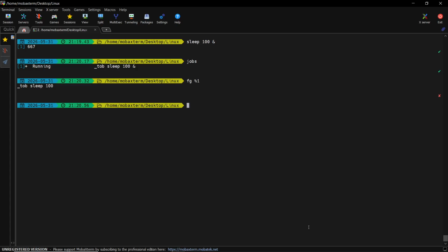Environment variables are important because many EDA tools and project scripts depend on them. If a required variable is missing or wrong, the compile or simulation flow may fail. So DV tools are often dependent on environment variables. To print the path, we can use echo and use $PATH.